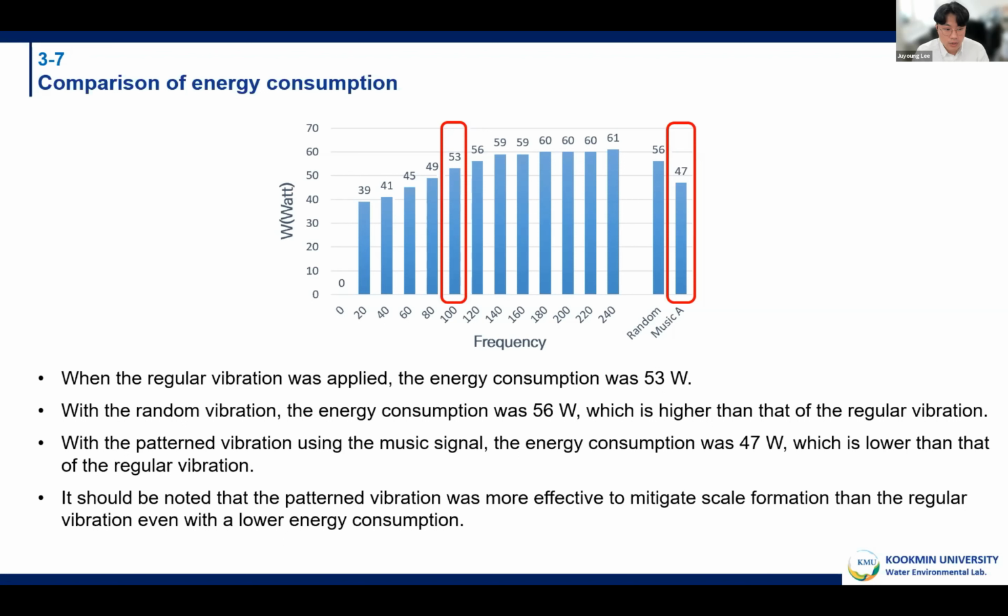With the patterned vibration using the music signal, the energy consumption was 47 watts, which is lower than that of the regular vibration. It should be noted that the patterned vibration was more effective to mitigate scale formation than the regular vibration, even with a lower energy consumption.